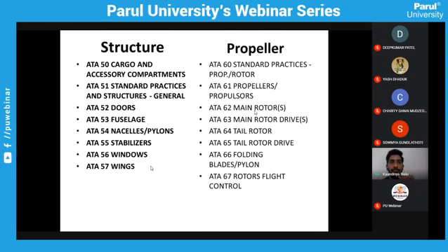Structures is nothing you don't know, right? Like stringers, web. I think Soumya, these guys know about stringers, what ribs are, what the difference is between longerons. Yes. So even though the components in the fuselage and wings have the same purpose, like taking the lateral and torsional or twist loads, every structural component is named differently for the convenience of replacing or repairing it.